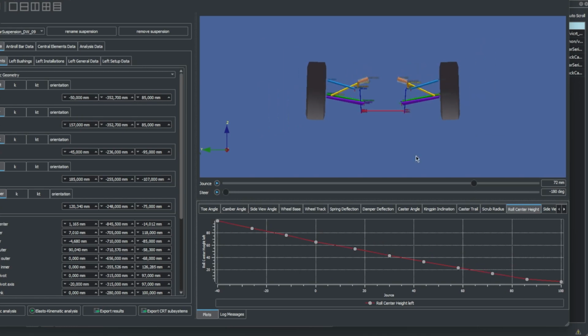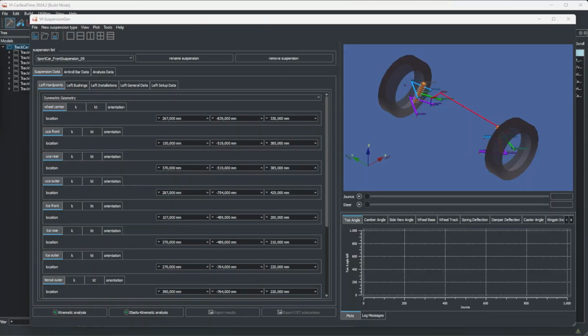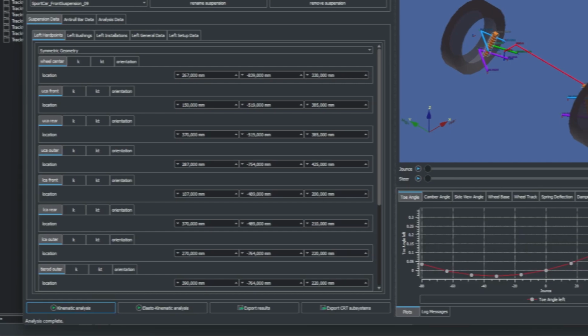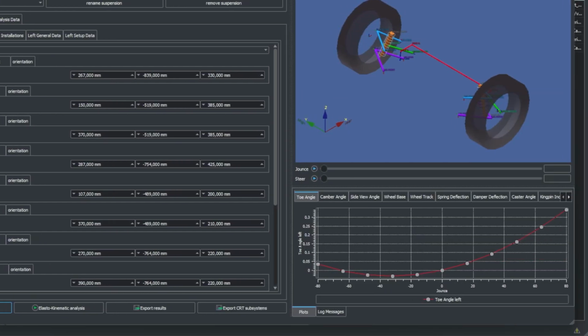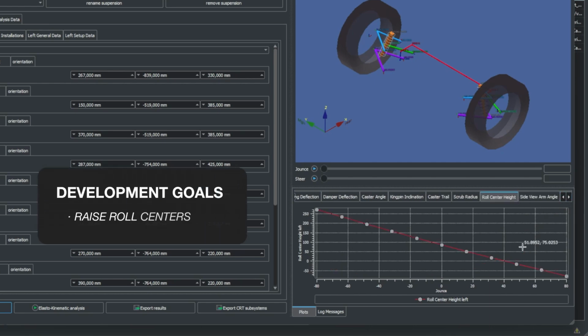Despite kinematics like this being acceptable, we can tune them to provide more predictable handling to the car, while ensuring stability and maybe even allowing for a little performance gain. We will approach this problem like this. By slightly raising the static roll centers, we expect to allow for the car to transition faster, while remaining less reliant on spring stiffness to control body roll.